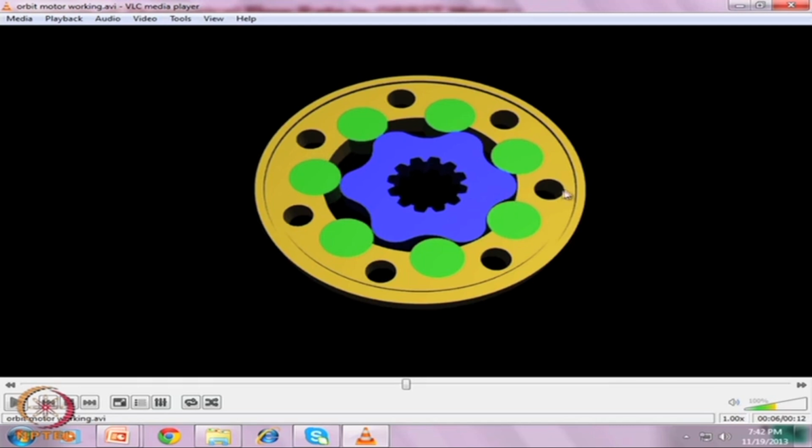So, what we can do is put the shaft rotational angle at 0, consider the 7th chamber, and calculate the volume. Next, after about 4 degrees of rotation, we consider chamber 3 and calculate the volume.